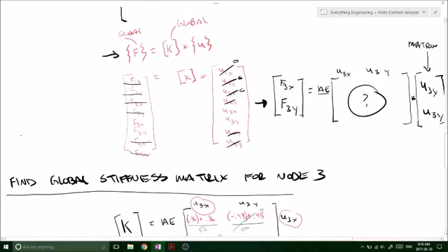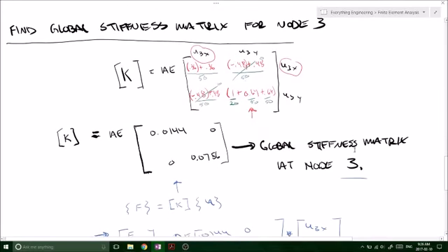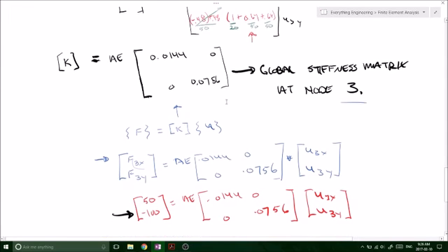So then we're looking at the global stiffness matrix, F equals K global times U global. We had no movement anywhere except for at node number 3. So we were able to just, for now, temporarily eliminate all of those rows and columns out, which left us with a 2x2 matrix globally for node number 3. Now to populate that matrix, what we did, we found all of the matching x and y components for our local stiffness matrix, and whenever there was anything overlapping, we added them up, and this gave us the global stiffness matrix at node number 3, right?